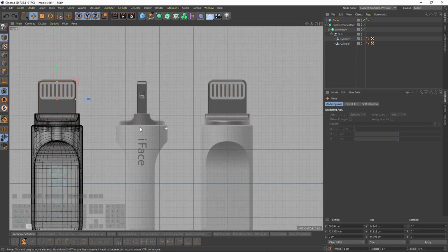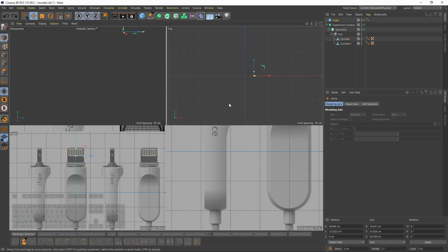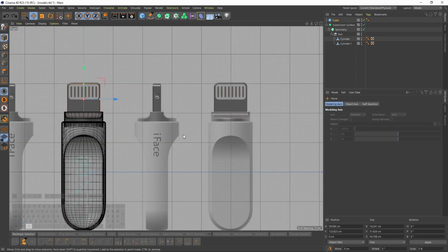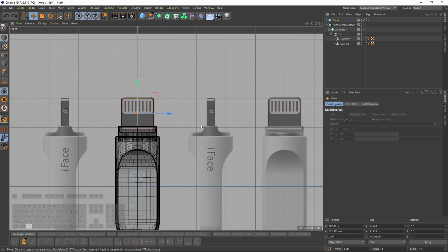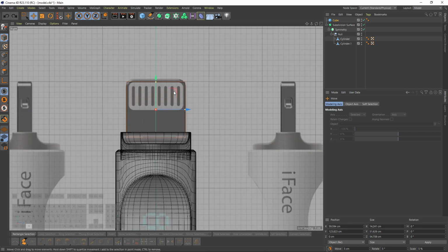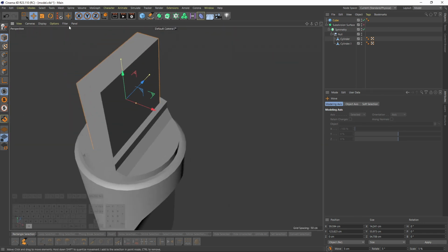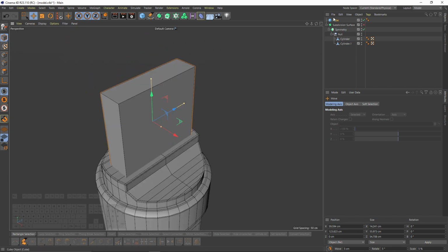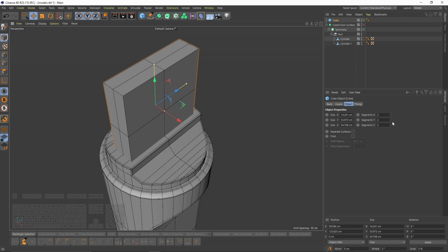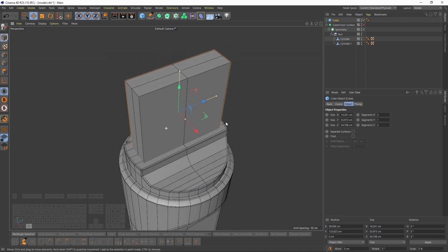So this is a general problem with image planes. So you need to pick one of them as your main image plane. And this time I will select that image plane because the bevels are visible here. Okay, now let's enable display with lines. Go to cube and I will give some segments, and I don't think we need Y segments. This is gonna be enough.